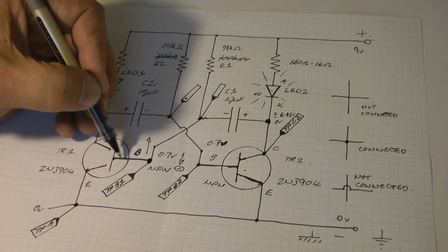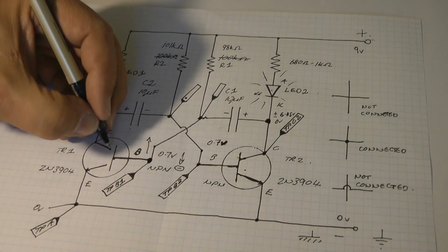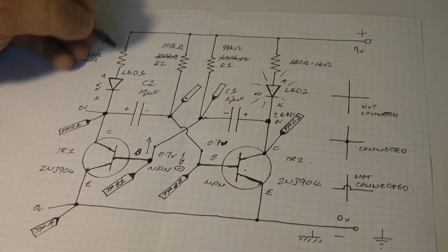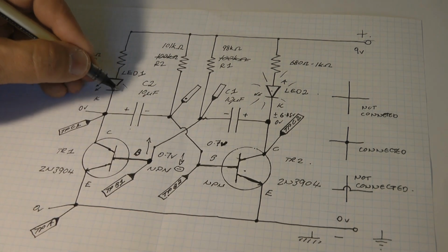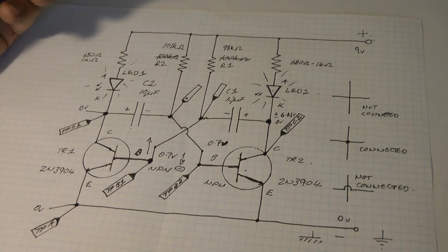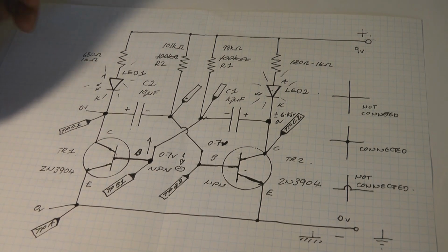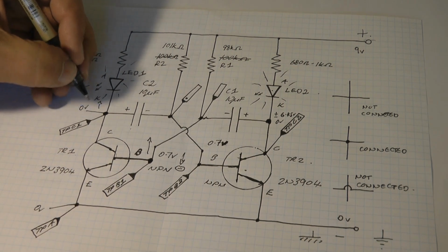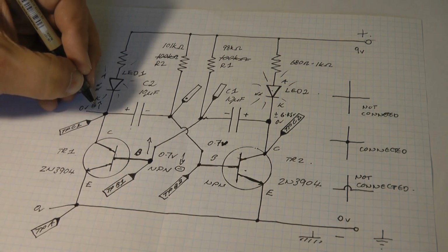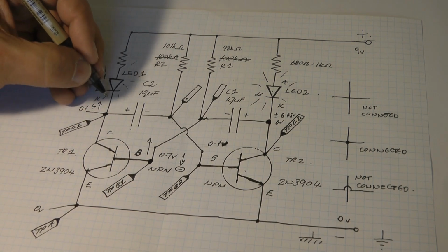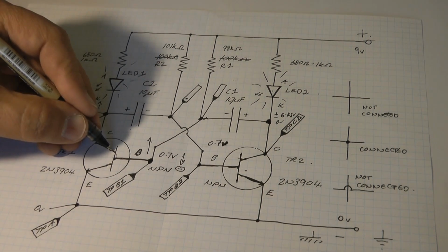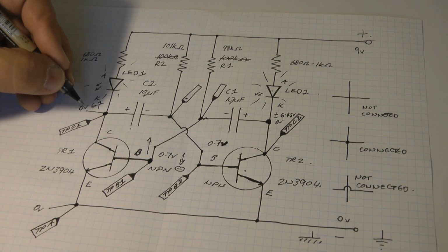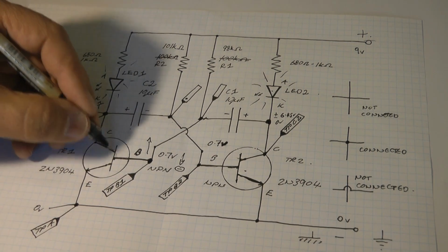And when this base recovers to 0.7 volts, what happens? The transistor starts to conduct again. And as this transistor is now conducting, the LED lights up on this side. And then what happens is, as this comes on, the voltage here, which would have gone up to, say, around 6 volts maybe, while this was open, drops straight away to 0 volts as this transistor comes on.